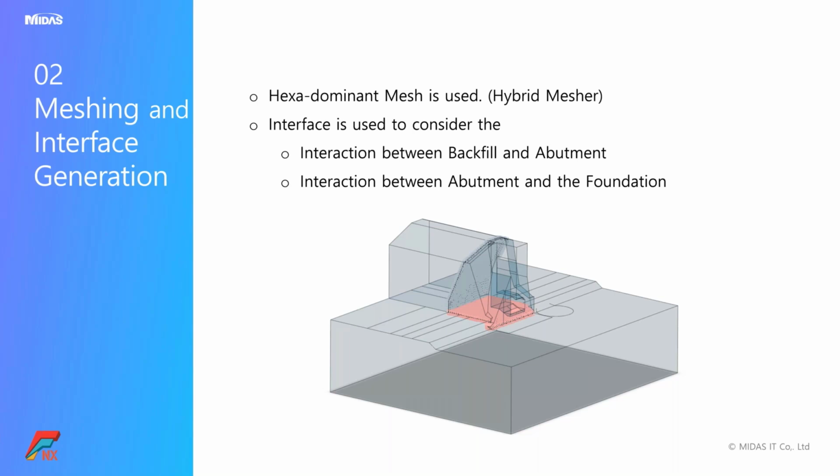When we use a hexa-dominant mesh, you will have a smaller number of elements, and when there are fewer elements in the model, the analysis time will be lower. The reason for considering analysis time is that we are running a seismic analysis, and whenever a seismic analysis happens, there is a huge possibility of a lot of time steps in the model, which may increase the analysis time.